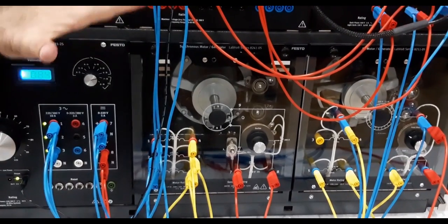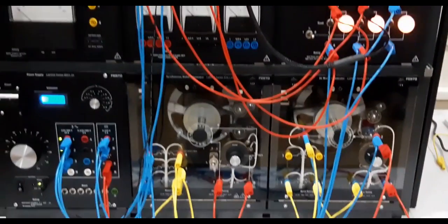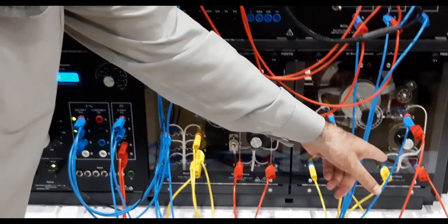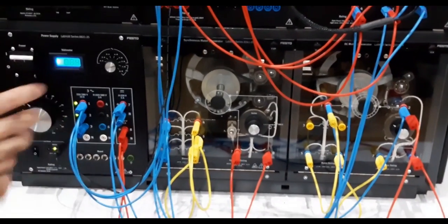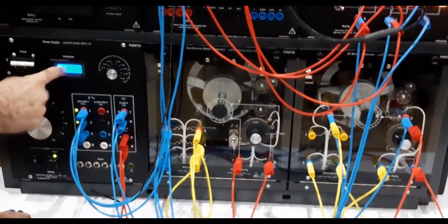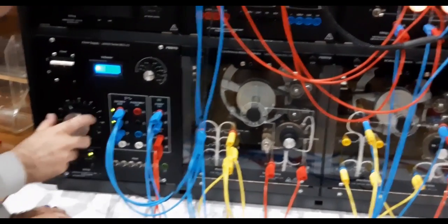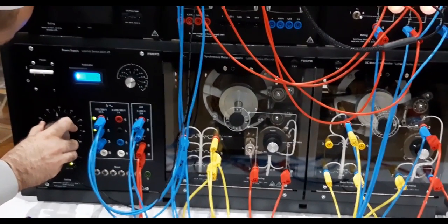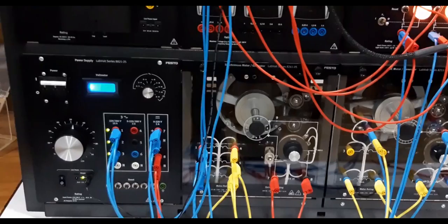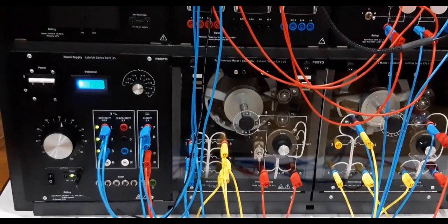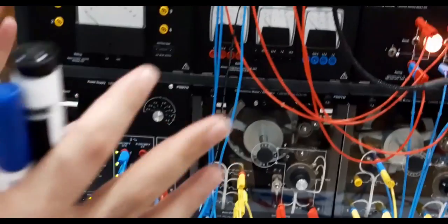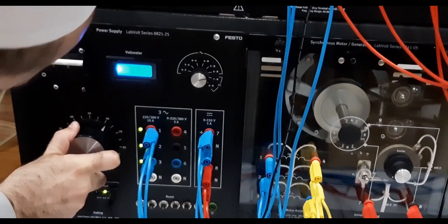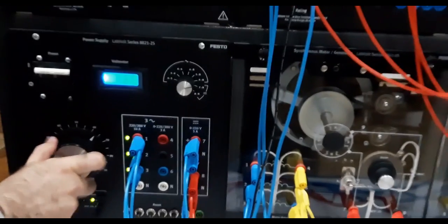And one can see here, as we increase the voltage, the speed of the machine increases, because increasing the voltage of the DC machine is one of the methods of increasing the speed. The speed increases, as you can even hear from the sound. As I discussed, we first increase the speed by moving the voltage to the rated voltage. So I will first make it the rated voltage. The speed is increasing.